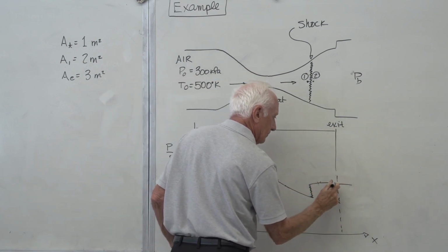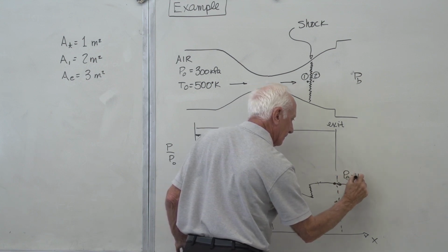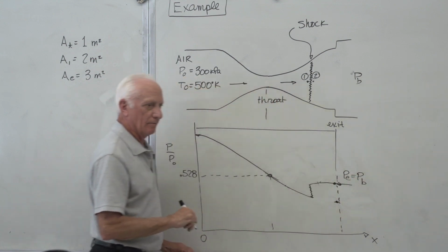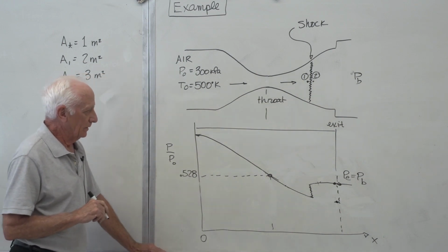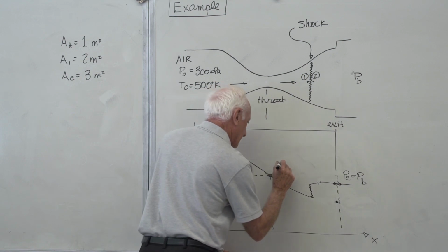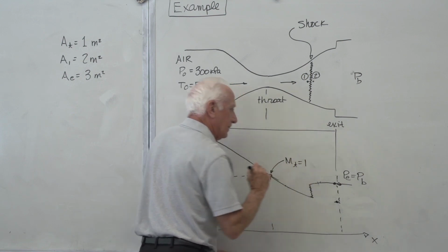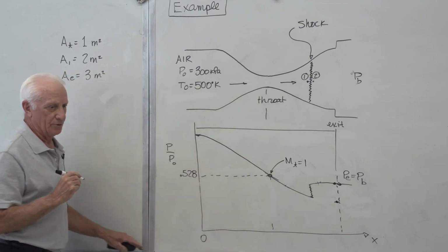Is P exit equal to P back? Yep. Because I'm on that curve. I told you why before. Did I reach Mach 1? Of course I did. Did it go supersonic? It had to. There's a shock wave there.